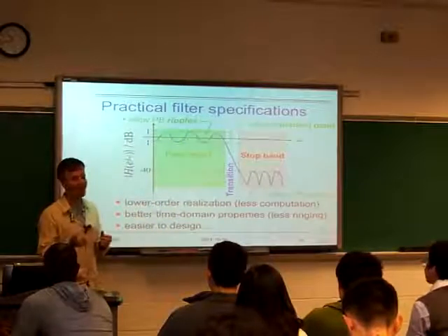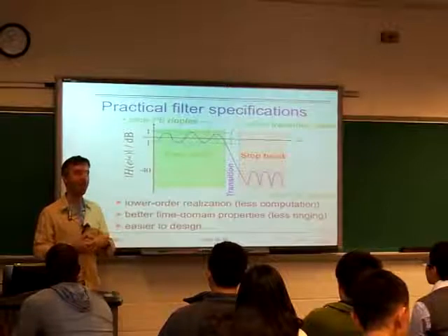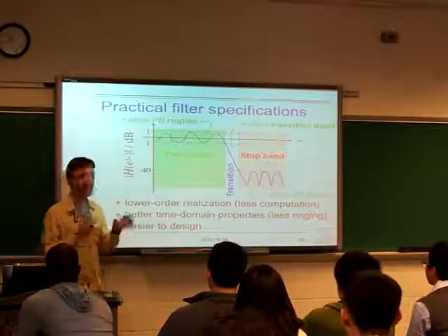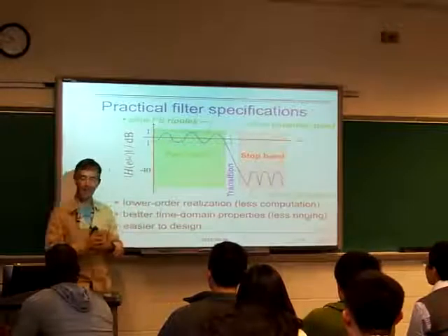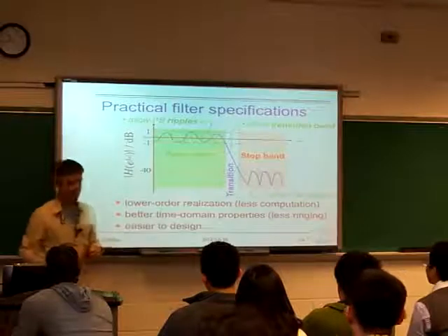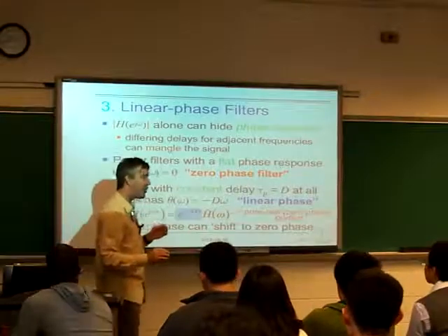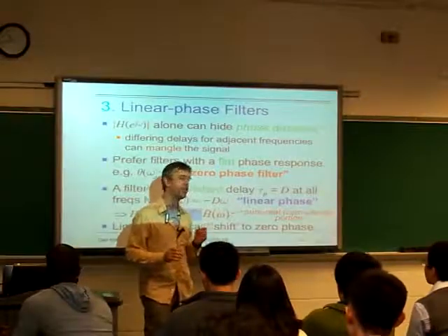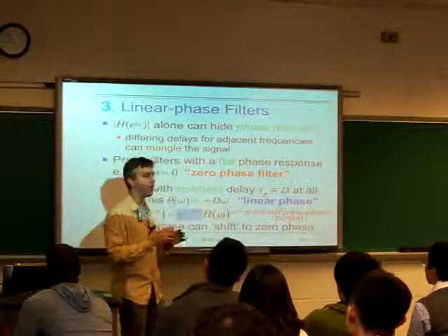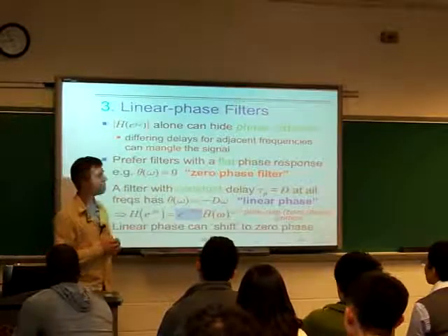Turns out in practice you normally can't do it. If you get a system with a lot of poles, then they become numerically very sensitive, and so you can't even build it if you want to. But given ideal computation, you could do it. Okay. So shooting for ideal magnitude response, in the sense of getting stop bands where no energy comes through for a whole range of frequencies, that's basically not practical.